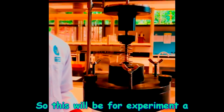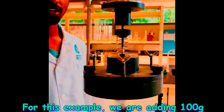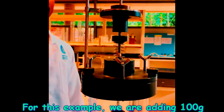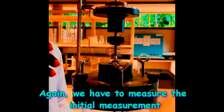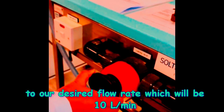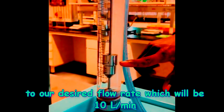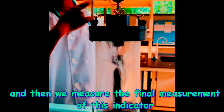So this will be for experiment A, and later on for experiment B we have to add in weights. For this example I'm adding 100 grams, and again we have to measure the initial measurement, and later on we have to turn on the pump to our desired flow rate, which will be 10 liters per minute, and then we measure the final measurement of this indicator.